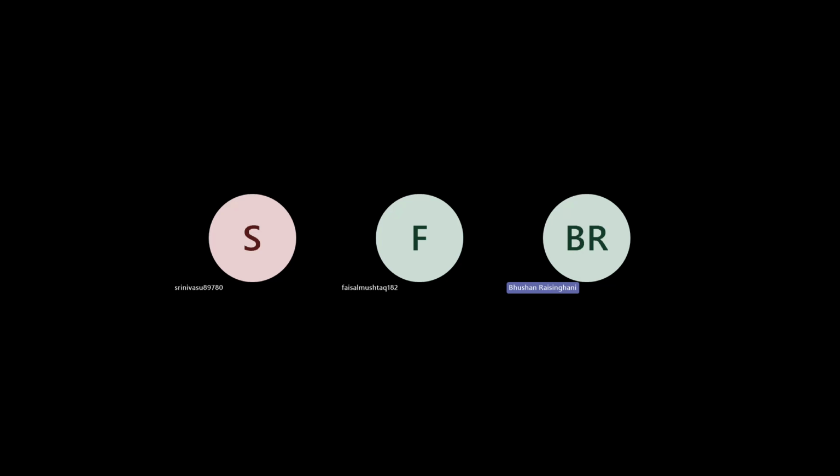And if it is more than 4, then it is a shear wall. This is the aspect ratio for shear wall. Then the plan aspect ratio for the floors, to be considered as a rigid diaphragm, should be less than 3. Like in the x and y direction, the aspect ratio should be less than 3 to consider it as rigid in both directions. Otherwise, we will not be able to take it as a rigid diaphragm action.